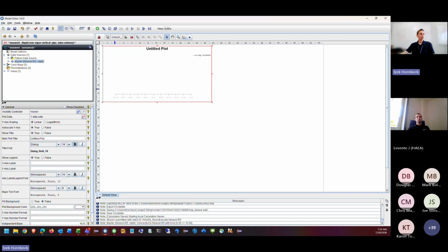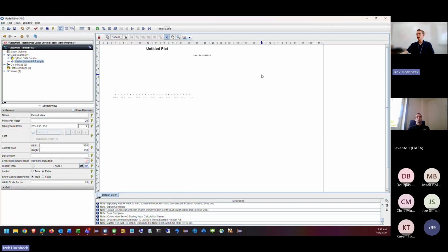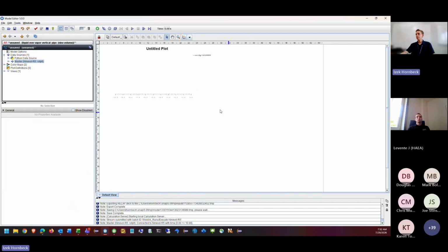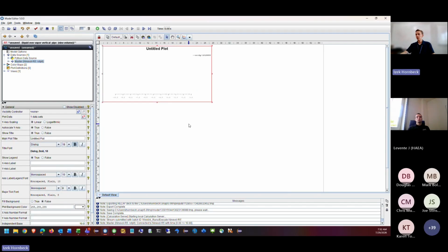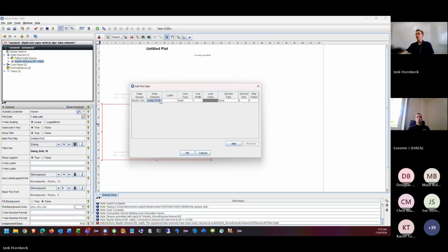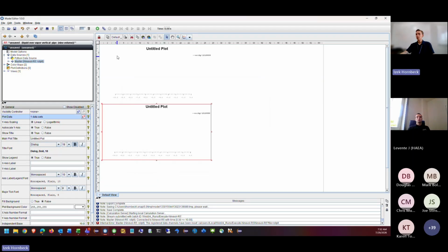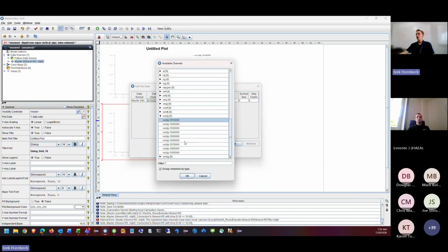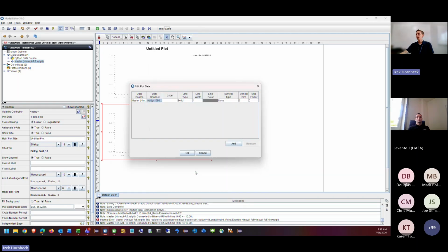So we're going to add another one. If you want, you can just create a new plot, or you can even copy this, Control-C and Control-V. Now everything else is set up how we want. We can just come in here and change. Oh, and you'll notice it sometimes becomes disconnected when you make some changes, so I'll reconnect to that. Now we can change our channel here. This one we'll choose our cell 9 of that same pipe to look at the void fraction in the bottom cell.